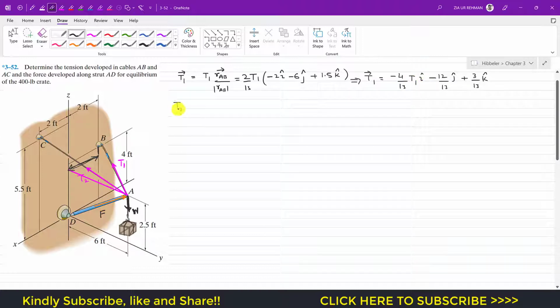Now T2, the tension in cable AC. So again this Cartesian vector will be equal to its magnitude multiplied by the unit vector from A to C, and the unit vector from A to C is the position vector from A to C divided by its magnitude. So this will be equal to T2. And now to find the position vector from A to C, we need to move along the x, y and z axis to reach that point C, and we need to find the distances along the x, y and z axis between point A and C.